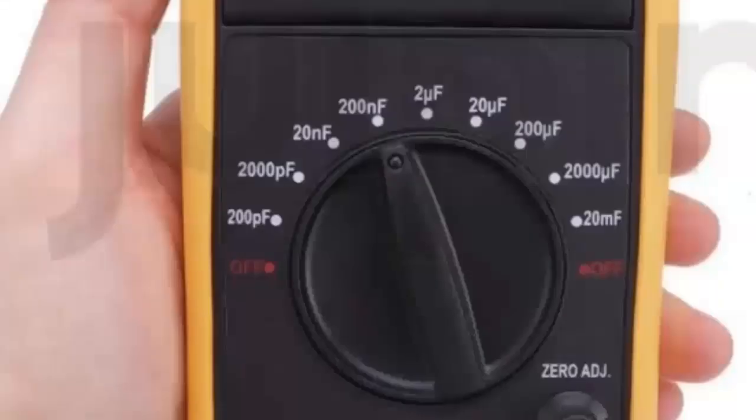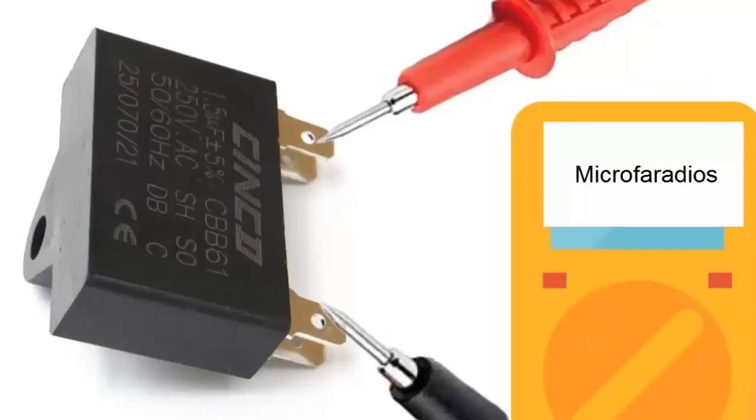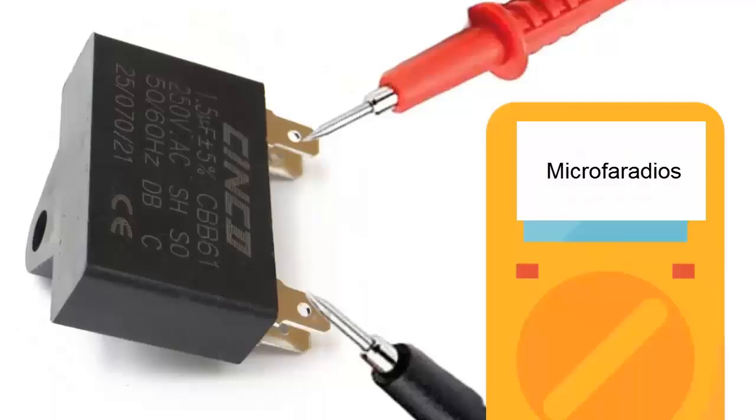5. Capacitance function. This function is essential for measuring the condition of the capacitors on the electronic board, the indoor unit's turbine motor, the outdoor unit, or the compressor. To measure capacitance, set the multimeter to the appropriate scale. The multimeter should include the most frequently used capacitance ranges for capacitors in refrigeration and air conditioning equipment.